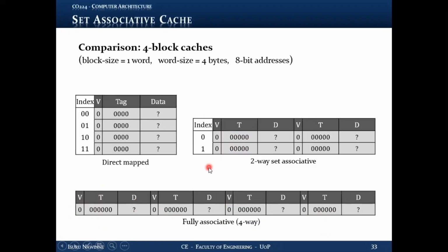Right, now let's go through some memory accesses. So the first memory access is this one. We have an 8-bit address here, 0, 0, 0, 0, 0, 0, and we don't know the offset bits, the exact bits we are using to refer to a particular byte. We don't know, and we don't care, right? We don't care about inside the word what is happening. So the CPU is asking for a word, and that is the address, right? So the part in black is the block address, and for different cache implementations, the tag and index sizes of these are different, right?